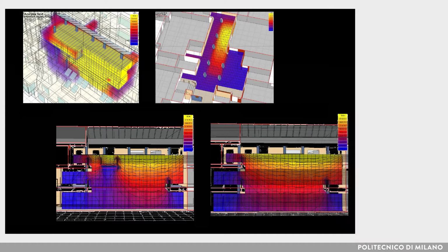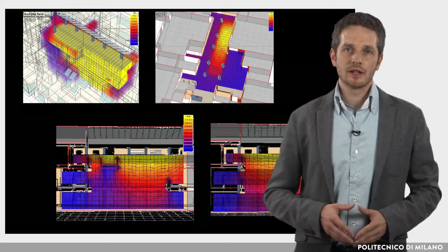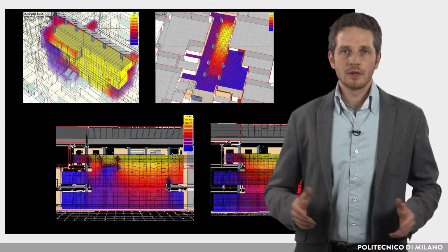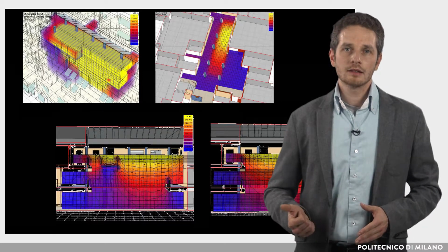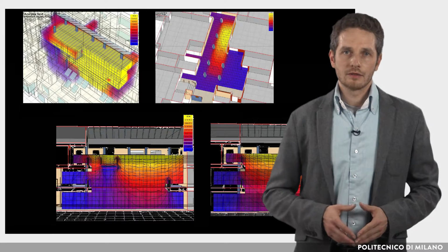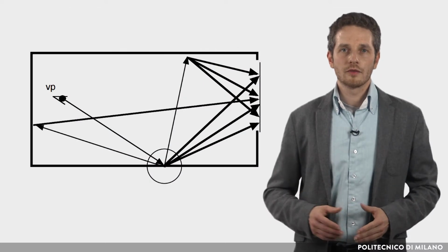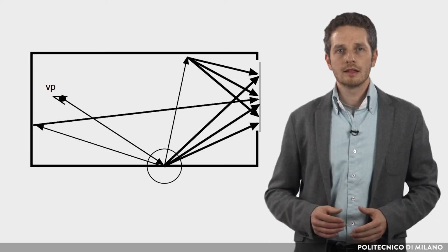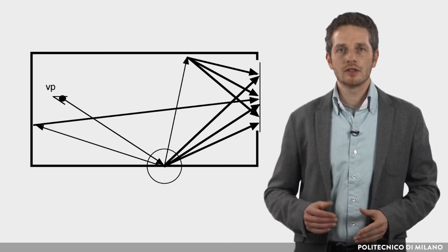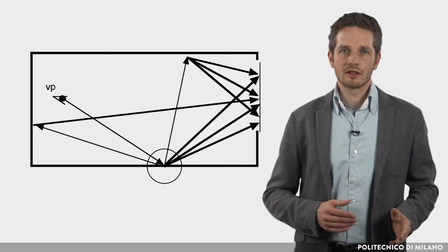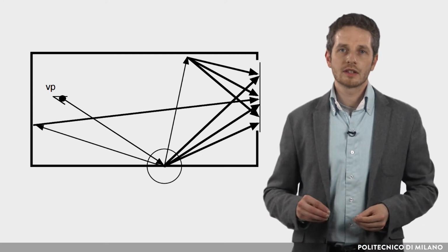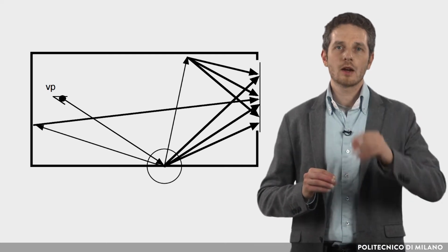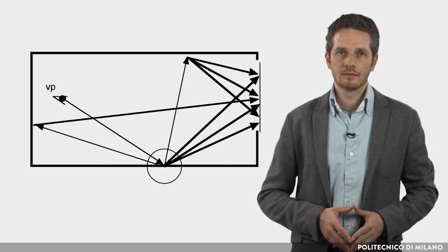be used. It calculates spectral radiance values, illuminance and color, for interior and exterior spaces considering electric lighting, daylight and interreflection. The major portion of the Radiance package is the lighting simulation engine that calculates light levels and renders images by using backward ray tracing technique, which consists in starting from a measurement point and tracing rays of light backwards to the source.